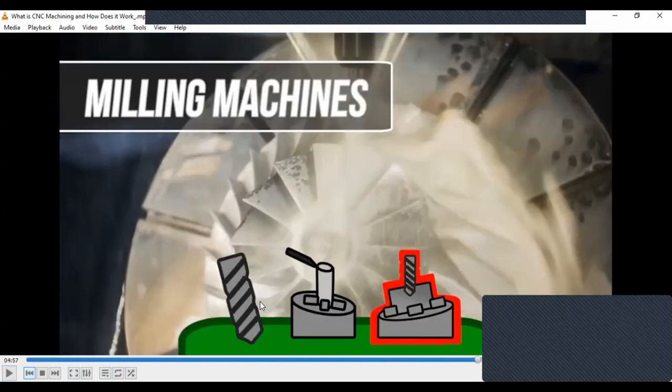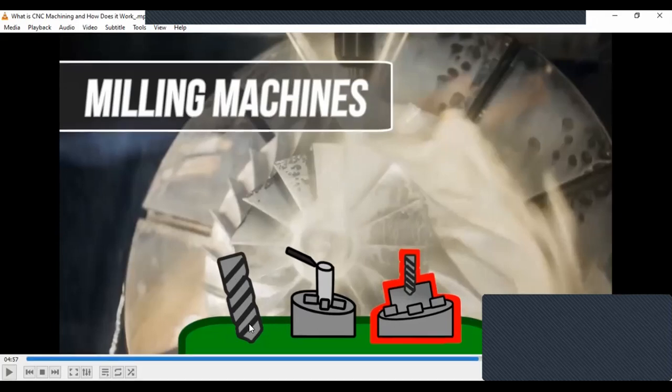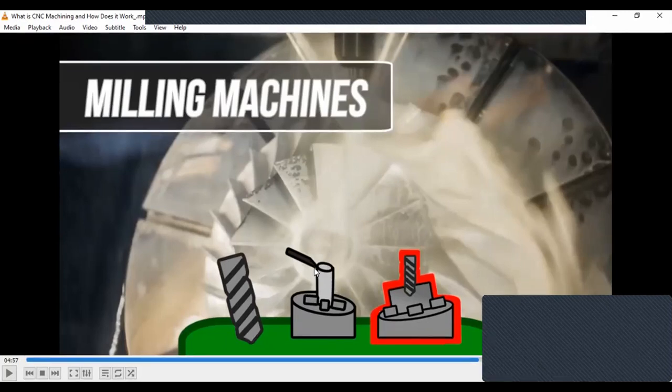You see, those are the 3 general CNC machines we have. Generally in machining, basically you have drilling, wherein the tool moves and the workpiece is stationary. In a lathe, the workpiece moves, and the tool only translates, it doesn't rotate.